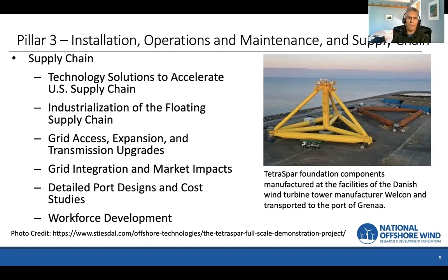And then the grid integration and market impacts topic area is about the integration of the whole system into the land-based grid, including other technologies and storage as well. We do that through production cost modeling, power flow modeling, and reliability analysis, to increase flexibility and reliability of the grid, or at least to maintain the current status quo of those reliability issues as we introduce more and more renewables.